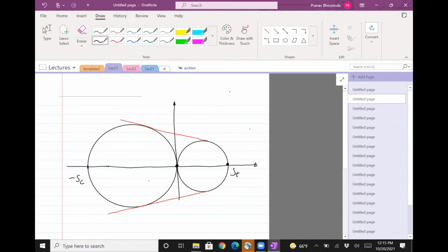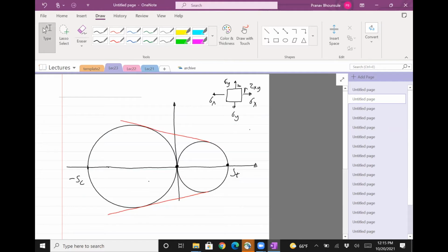Okay, so let's assume that we are interested in finding what happens to an object or an element that has a general stress distribution as so. Okay, so we have that, and that's given to us. We need to figure out for that particular stress distribution, which has shown that plane stress distribution, will it fail or not. So the first thing you want to do is take the stress and find the principal stresses from here.